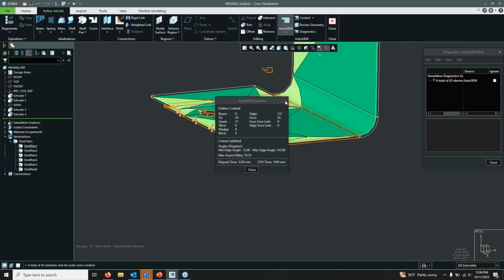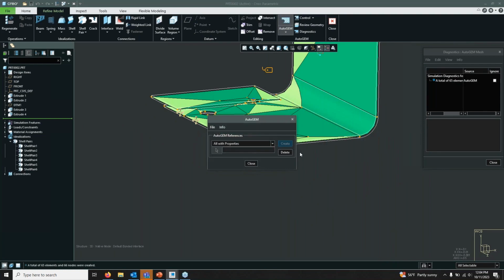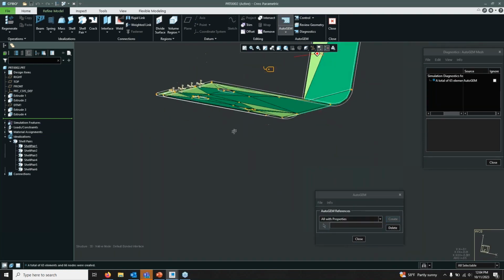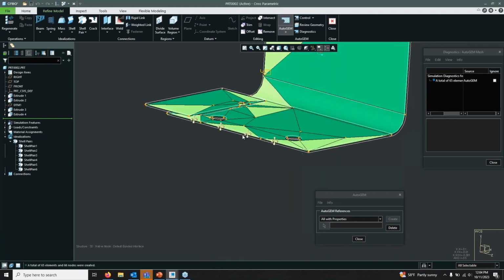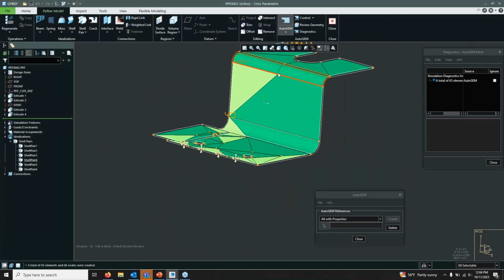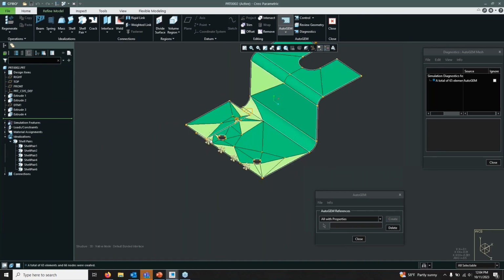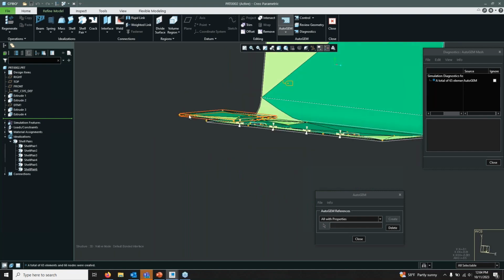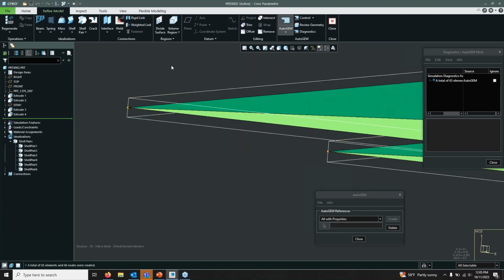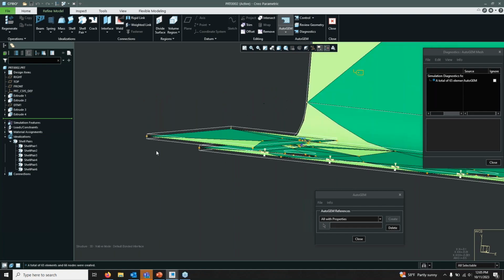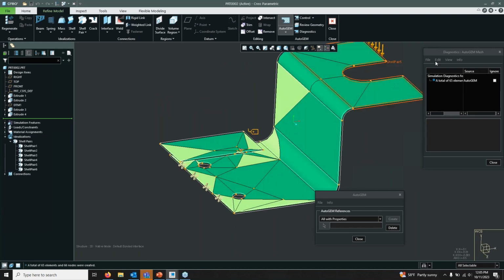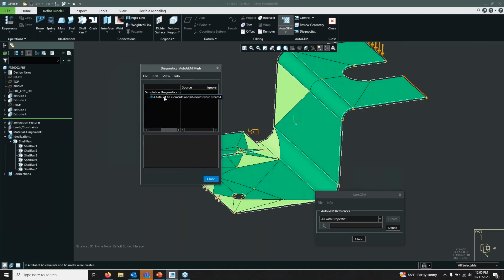If I mesh this, so that was step 5, create my mesh, we'll notice that this is meshed with 2-dimensional shapes. So quads and quadrilaterals and triangles are going to form this 2-dimensional mesh. And this is going to be much, much simpler than meshing this in 3D. So if I did not create a shell, I would have many more elements than 65.